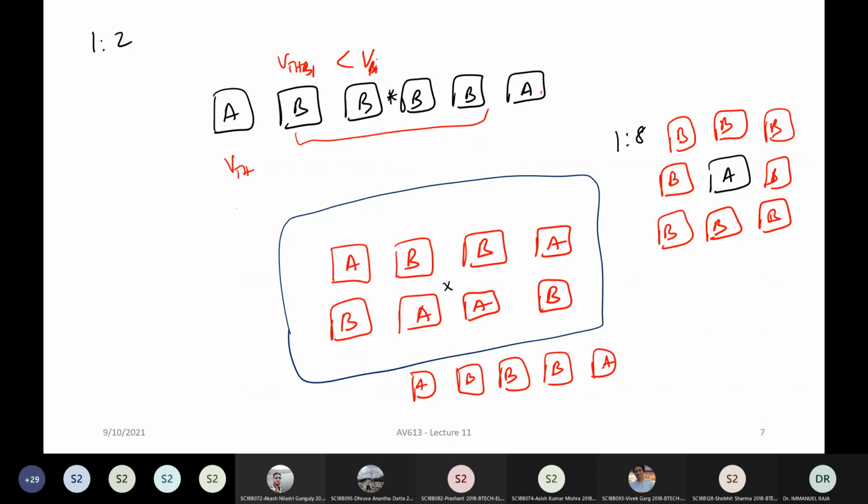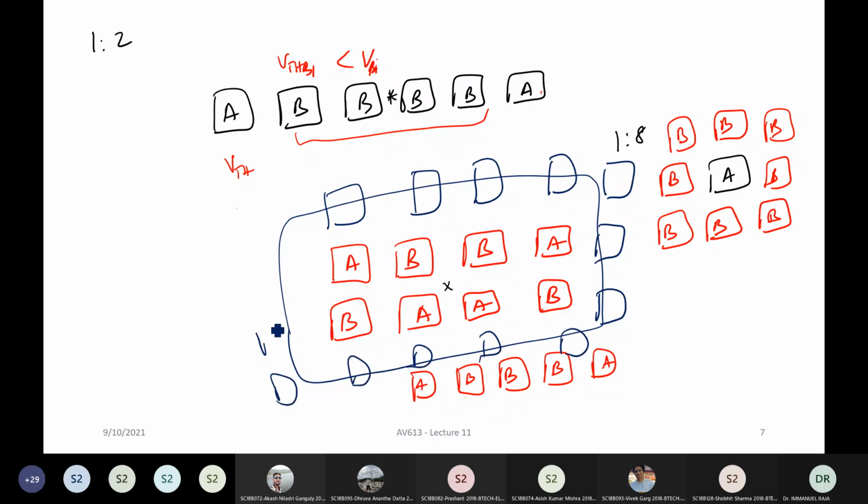It's totally a dud device. It does nothing. It's basically a sacrificial device. It sits there taking all the blows, making sure your actual device is protected. So you basically have dummies all around, usually a ring of dummies all over the place.